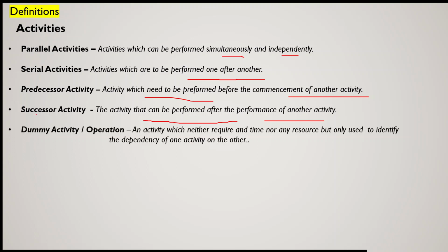Then there is another type of activity that is known as a dummy activity. A dummy activity is an imaginary activity which neither requires any time nor any resource, but is only used to identify the dependency of one activity on another activity. That means this activity may not be directly related to the other activity, but till the previous activity is completed, you cannot start this activity.